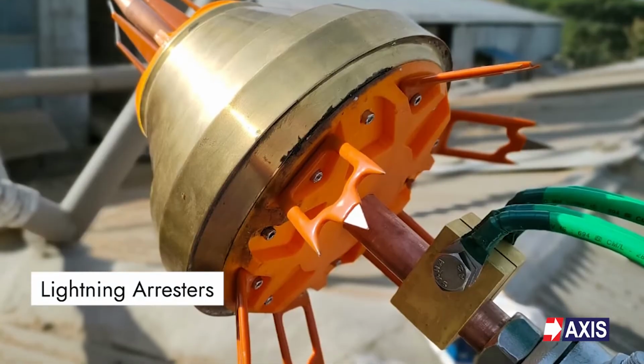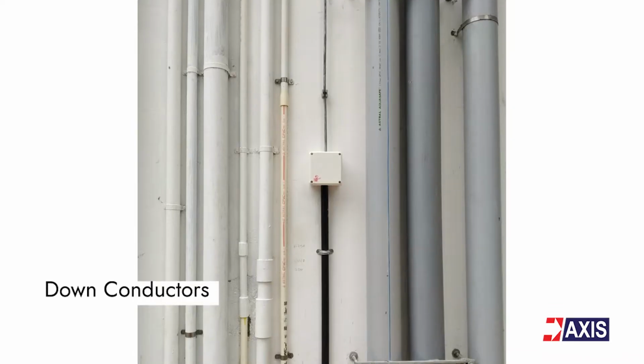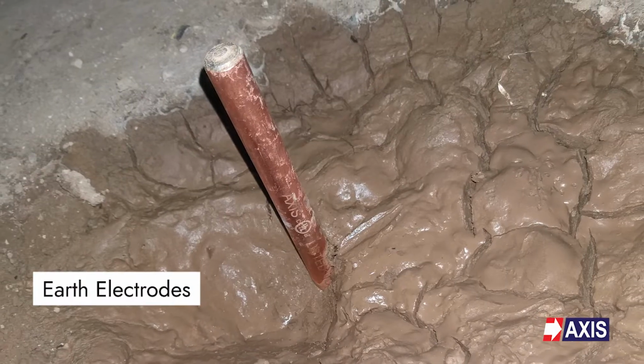The lightning protection system design that we get at the end of using the protective angle method or the rolling sphere method or the mesh method will provide information to the system installer, such as the location of the lightning arrestors, the location of the down conductors, the earth electrodes, any other equipment, and the complete bill of material needed for lightning protection.